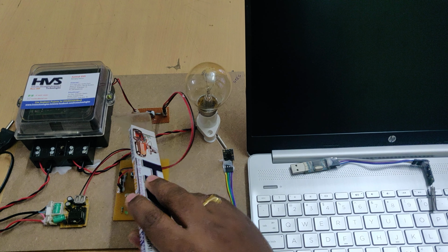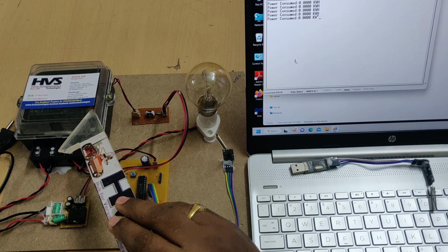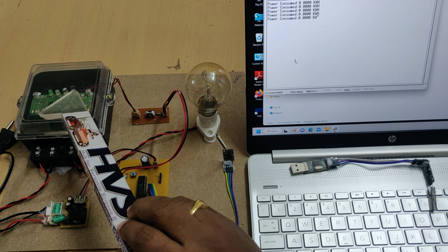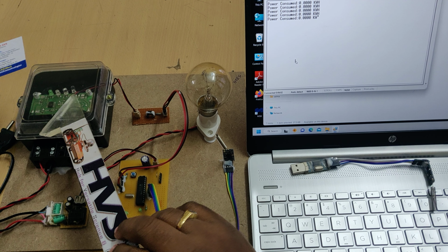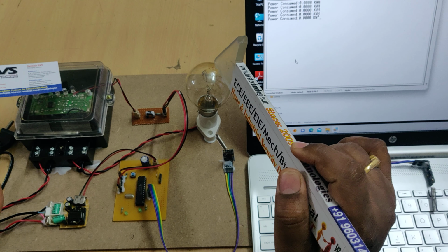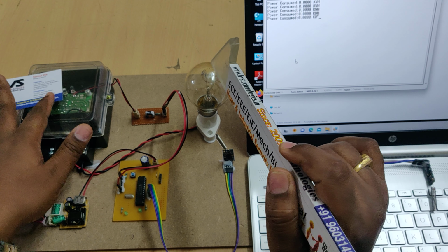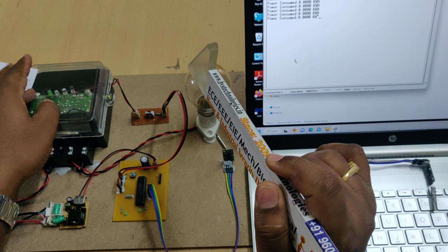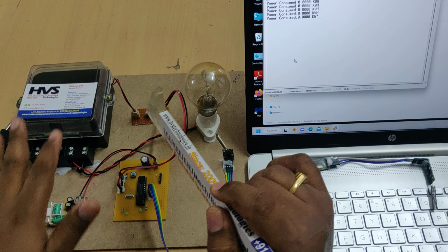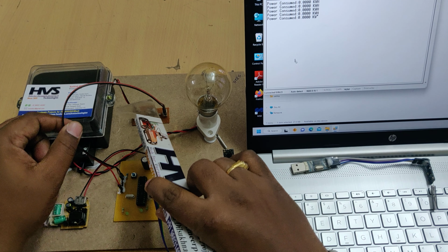The optocoupler's purpose is to read the data from this energy meter. The energy meter consists of LEDs, and one LED shows the status of the load. When that particular LED reaches 3200 blinks, it is an indication that 1 kilowatt hour was consumed. So proportionally, one blink is equal to 1 by 3200 kilowatt hour. That is the ratio for each blink, and it will be identified by this PC817 optocoupler.